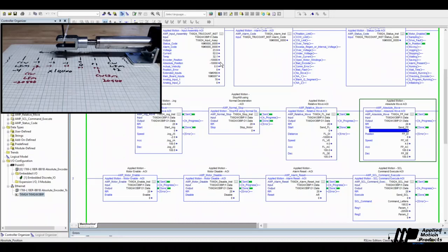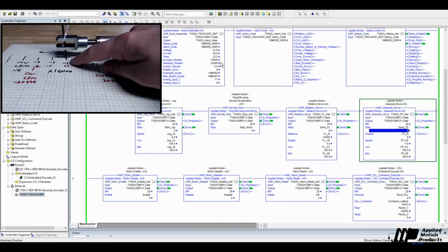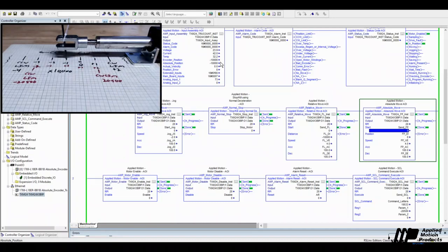Oh no, we're back to -10,000. We're back to our initial position. That's not great. Why did that happen? That happened because we did not save the values. So we can make all the changes we want, but until we send the SA command, the save command, they're not going to be saved in non-volatile memory. They're going to remain volatile numbers.